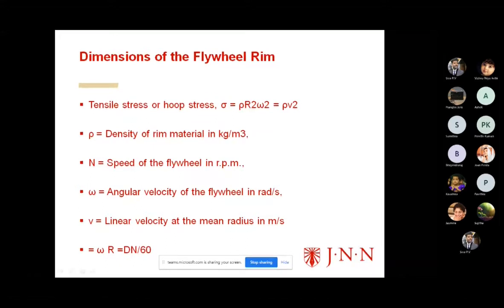Even if you take an IC engine, in our two wheeler, four wheeler, automotive, the IC engine has fluctuation. First is the suction stroke, second compression, third expansion, fourth exhaust. Only during the expansion stroke is power obtained, but during the remaining three strokes the power is off.